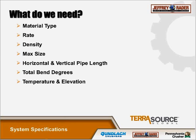Temperature and elevation are very important. It's going to affect the air density. As an example, air at 2,000 feet is going to be 7% thinner than at sea level, and air at 100 degrees Fahrenheit is about 5% thinner than at 70 degrees Fahrenheit. If you don't take this into account, your system might operate in the morning, but then not in the afternoon when it heats up. So at Jeffrey, we always make sure that that is accounted for.